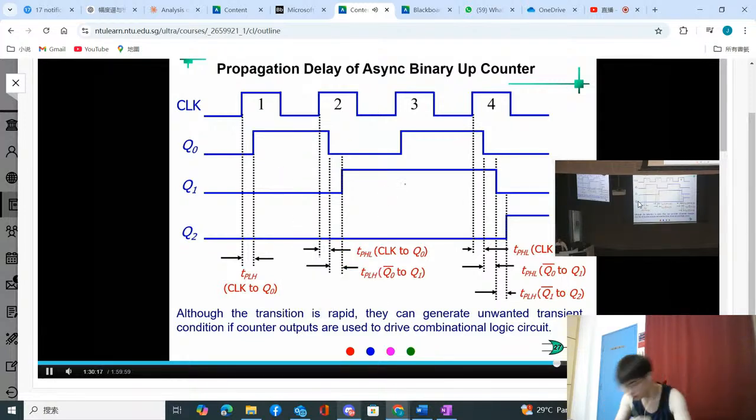It means that if you have, for example, an AND gate, and one of the signals is going low to high, the other signal is high to low, because of the difference in delay. Because 0, 1 will give an output of 0. While during a short period of time, it might give an output of 1 because of the different delay. And here, because of the different delay, the output is 1 at this point. You will consider this a race condition. A race condition means that you generate a glitch because of a different delay.